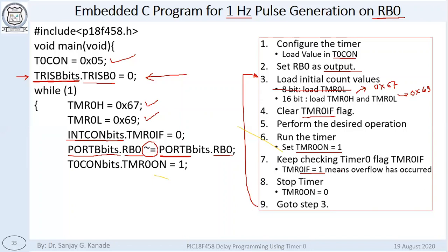And how to implement that? You have different ways. Of course, you can use some of your own logic, but the simplest and shortest way is by using this. See what I have written here? While INTCONbits.TMR0IF double equals 0. This double equal sign means comparison sign. This is asking, is it equal? This is standard C syntax, right? Standard C comparison operation.